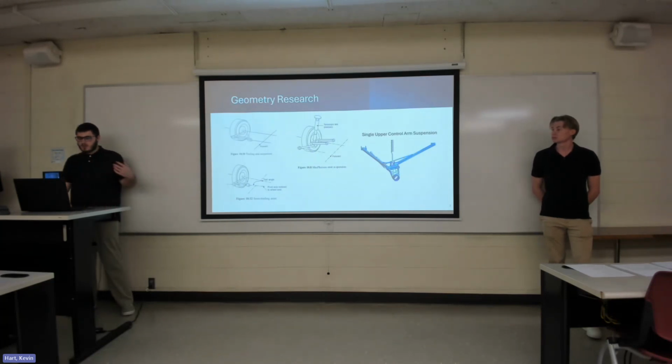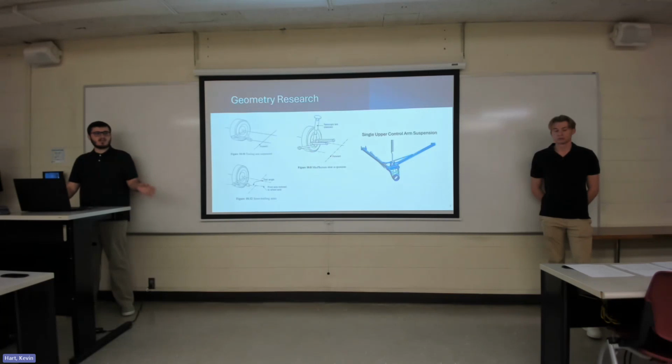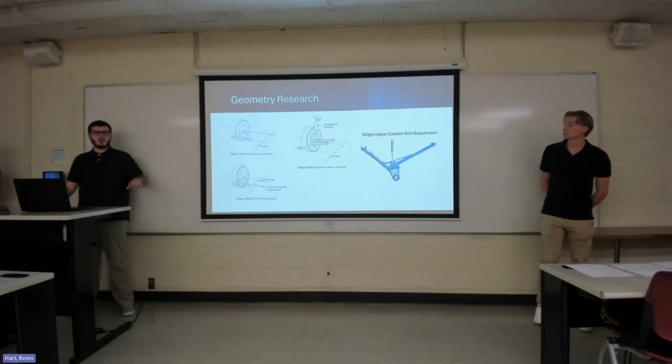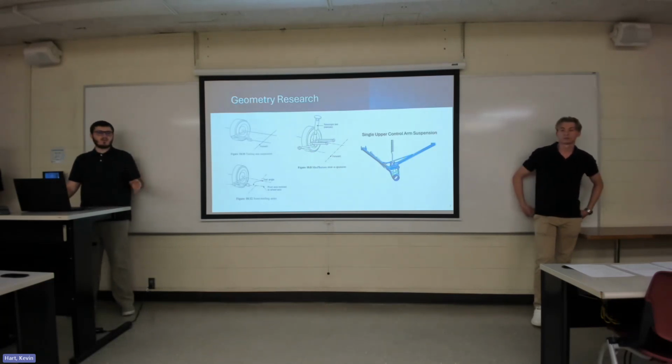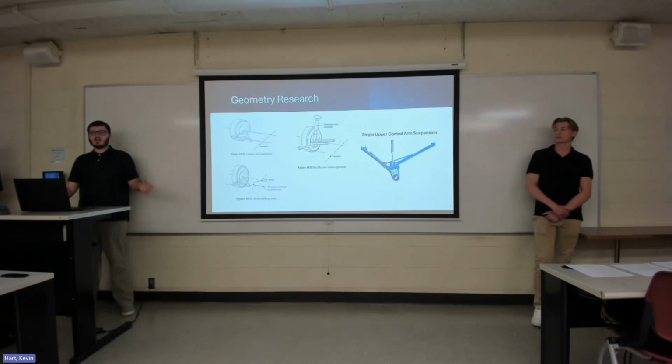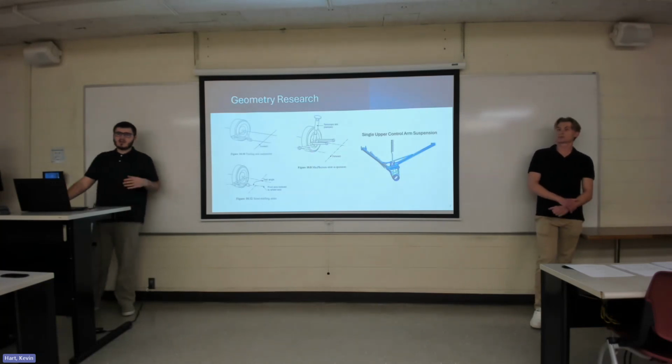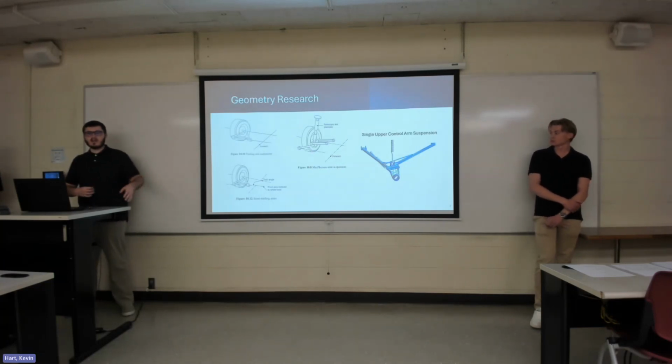With the implementation of a load-bearing axle, which utilizes U-joints instead of CV joints, which the drivetrain will cover in more detail later, the lower linkage of the double A arm can be removed, yielding just a single control arm. That gives us the lightweight benefits of only having one control arm while still having the ability to optimize negative camber while still yielding almost no toe gain.